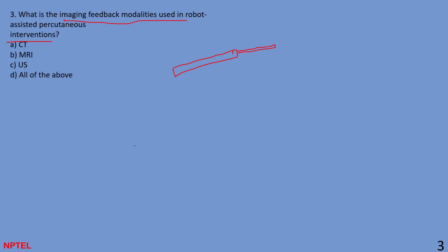And you wanted to bend this needle in real time, right? How to do that? And you wanted to bend the end effector, like this. You can bend it, but you wanted to know what the end effector position is, right? So that this actual position can act as feedback for your control, so that your motor can change accordingly in order to, let's say, reach some position.